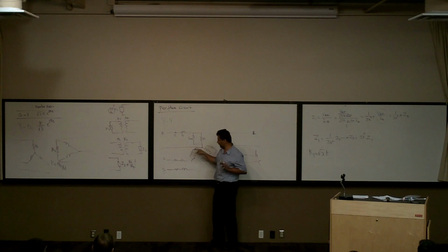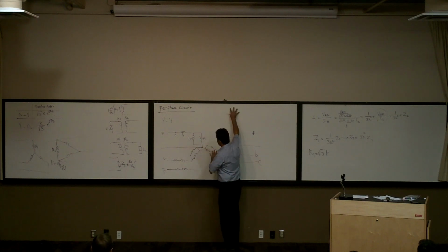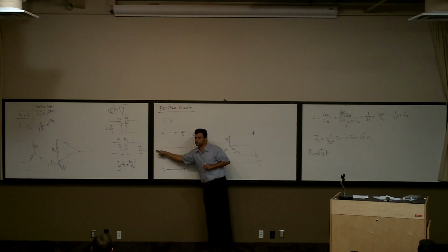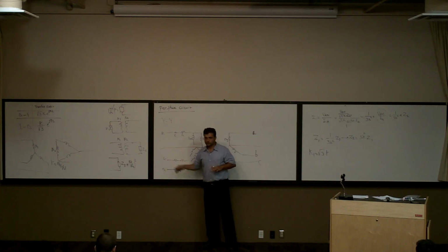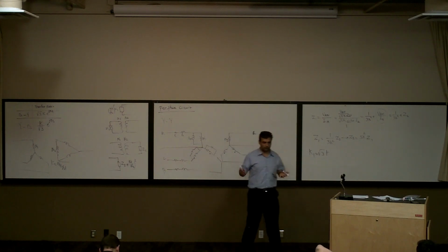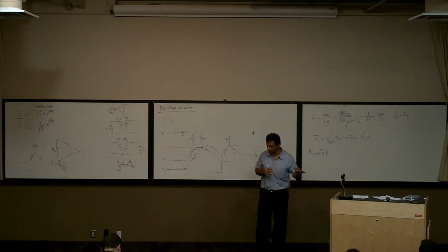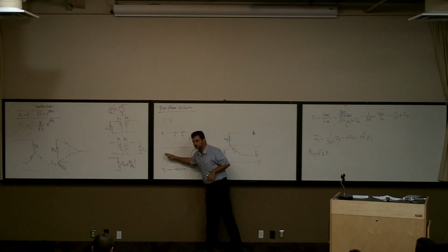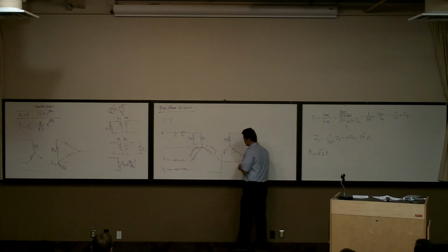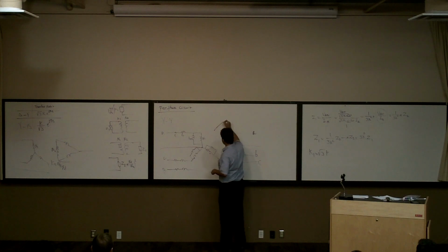0. So basically, when I put it here as a single phase, you see, hey, there is a current in this wire. Don't be surprised. This wire is not carrying any current, but I'm doing it only for one phase, right? When I put all three phases together, the current in this wire will be how much? Will be 0. So basically this one, a single phase, would be as simple as this.